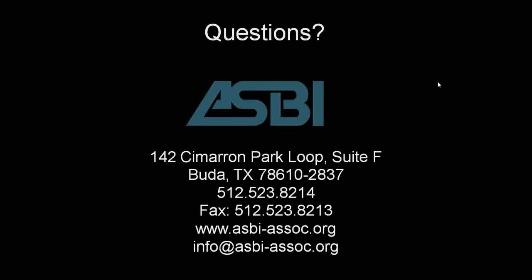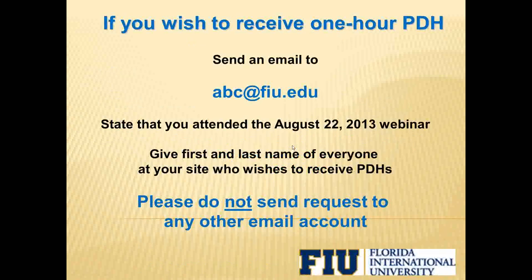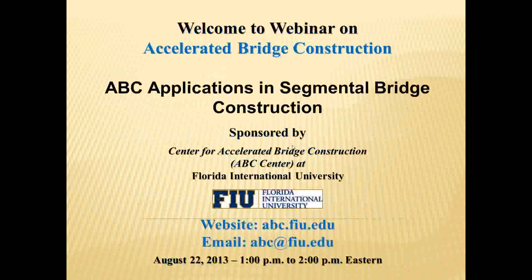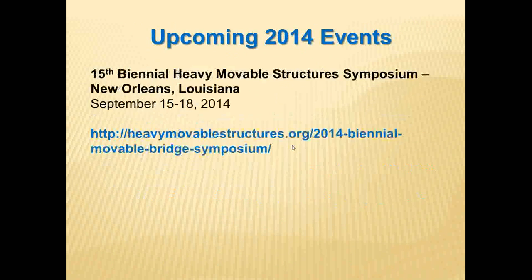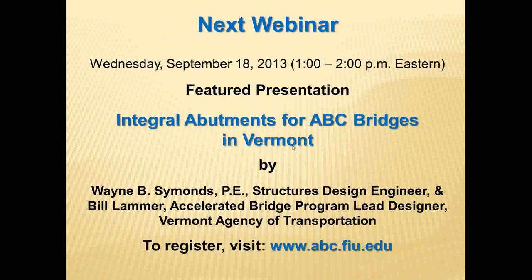A protection level PL2 tendon requires a plastic duct, a grout cap, which is installed over the end of the tendon. It has certain requirements in there for the grouting ports that require positive shutoffs, etc. So that creates the airtight system.